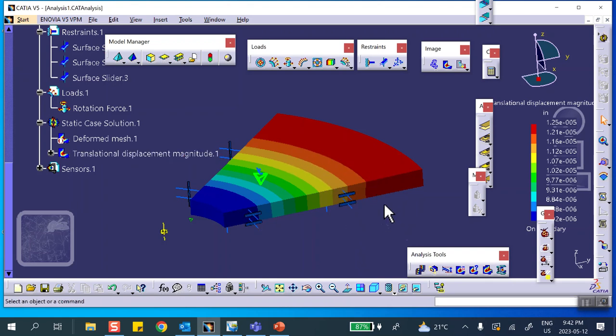You can see why, because these are all radial, circular contours. Okay, good. So the amount of deflection, of course, is very small because this is a 1-inch thick piece of steel, 1,000 RPM. Yeah, we don't expect a lot. This, by the way, is inches. You can go and change these things to millimeter, meter, whatever you want.